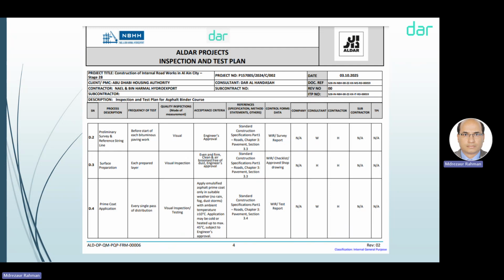Depth for the thickness of the asphalt. How much depth for this? No, I'm not talking about asphalt actually, before starting prime coat. Before starting prime coat, our contractor submits surface preparation and survey to check the level and camber. You are doing this during the inspection of roadways? Yes.